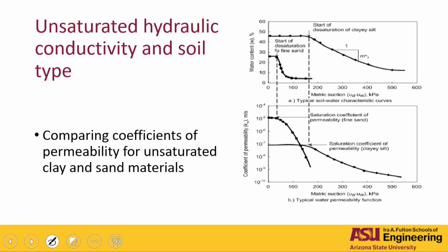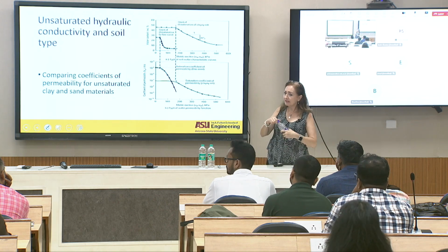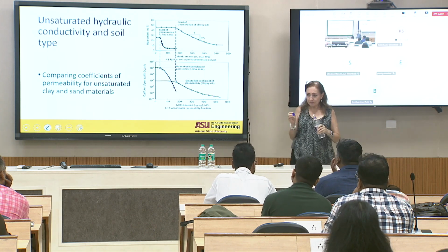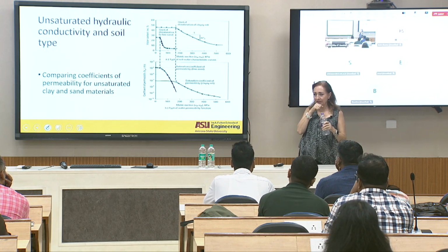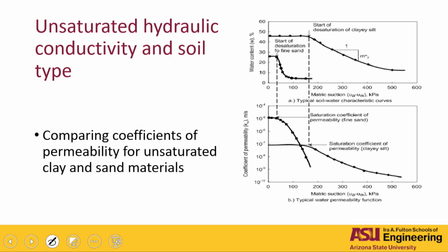For example, if you talk about saturated hydraulic conductivity, which one is higher? The saturated hydraulic conductivity of a clay or of a sand? Depends upon the saturation. Sand. It's going to be sand, excuse me. Saturated means suction zero. So you got that. And what happens is, if you compare both suction curves, both SWCCs or soil moisture retention curves,